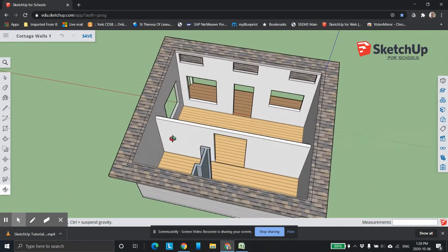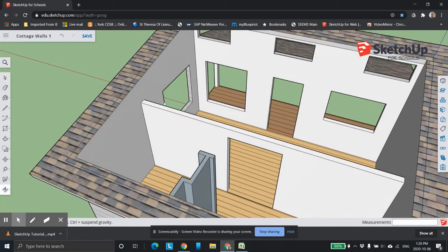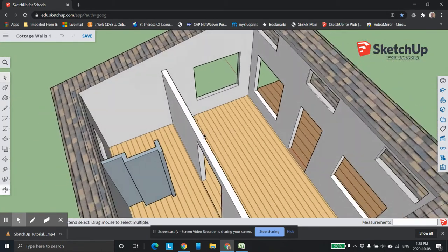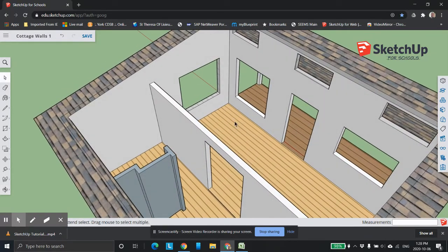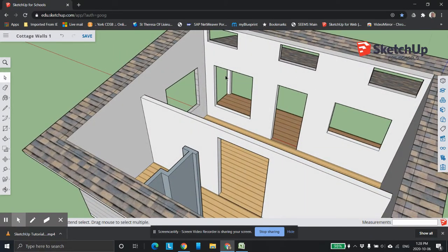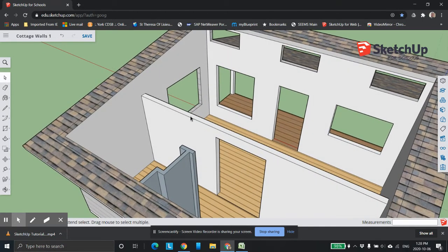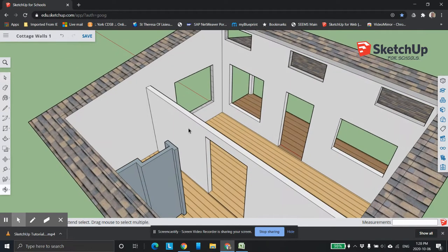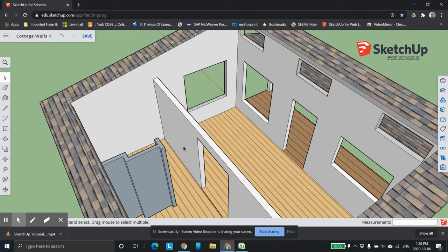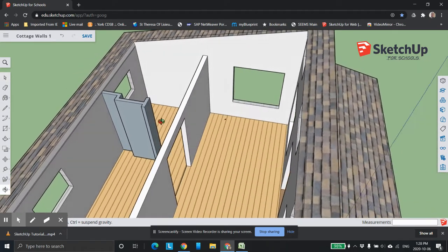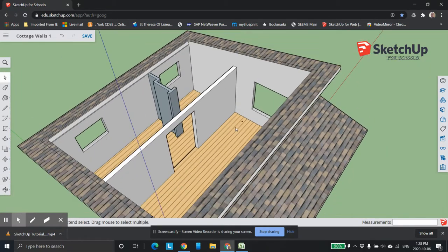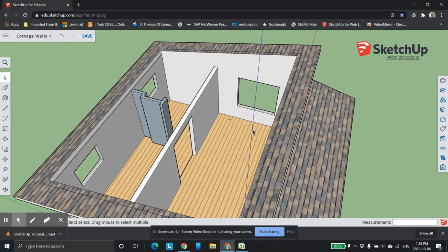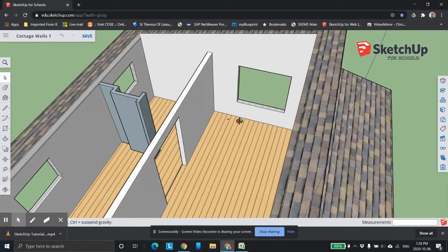And you can come in here. I might have discussed in the last video, I can't remember. This cottage would be heated by a wood stove, which we're going to put right in here in a few minutes. But one of the things you have to be aware of is there's no furnace in here, and there's no ductwork and so on. The reason this wall is low, and yes, we did discuss it in the last one, is because you want the heat to be able to come up and over the top. If it was right to the top and you had your privacy door closed on your bedroom, you'd be getting no heat whatsoever. So this is indicative of a very small cottage, one that's maybe just used up till October, and then they shut it down in the wintertime and go home, that kind of thing.